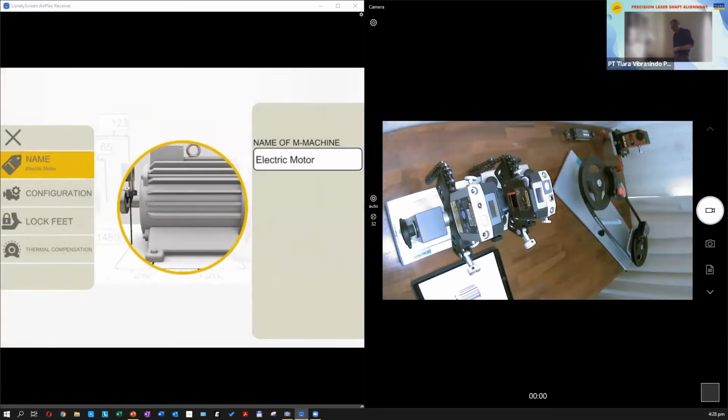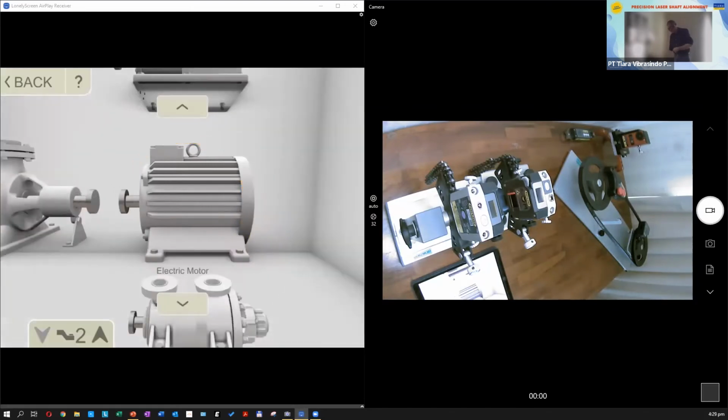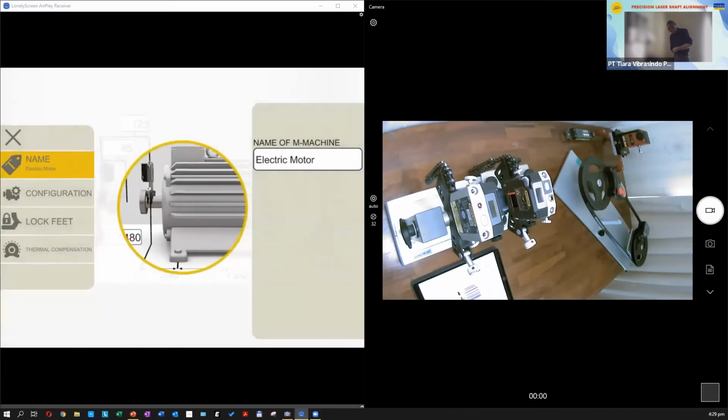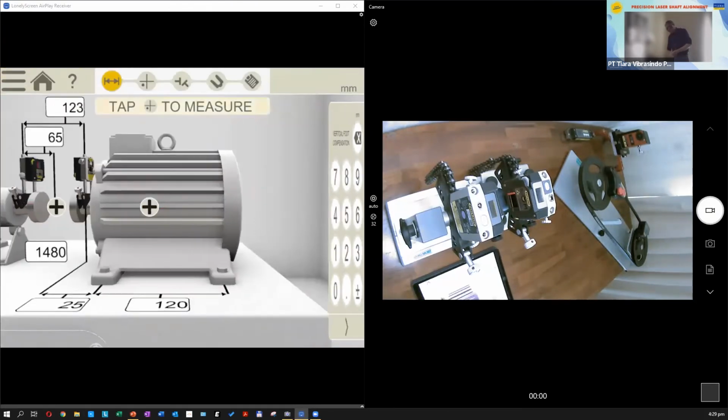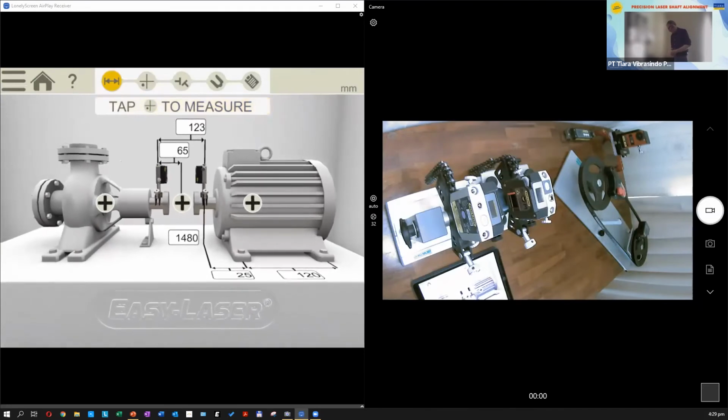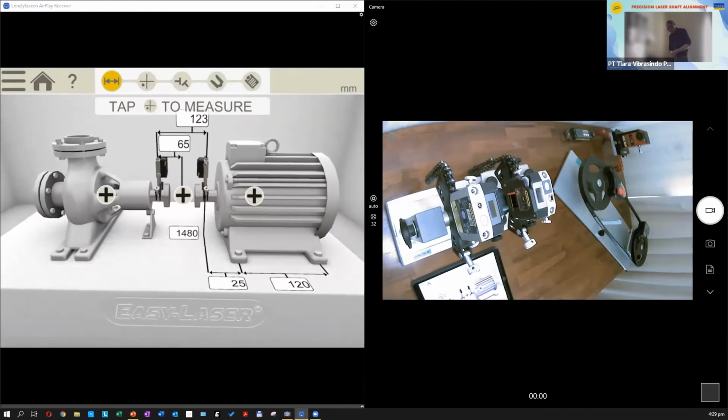That is our motor, with the same configuration that I can change here. I go further and say, here is my temperature growth, for example, my offset between hot and cold, that you can key in. You can, of course, measure it and then transfer it into this reading right away. And the last point refers, besides all the dimensions, to the coupling itself.